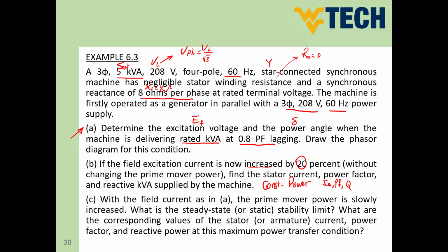So, for instance, if you are working in a site and you get a command to increase the power by 20%, you have to see where you are working right now. Will increasing the power 20% more make the machine overloaded and reach the maximum condition? Because this may burn your machine.